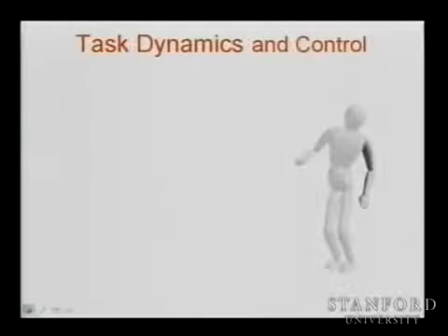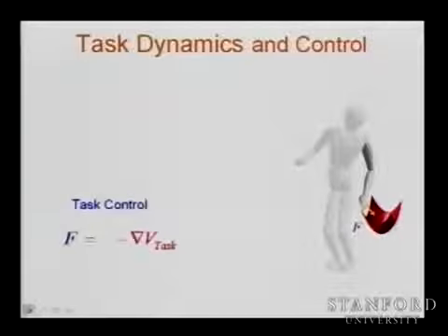Let's go to the arm. That's what we studied earlier. You have a force. You have the gradient of the force. How do we apply it? Torque equals J transpose F. Okay, very simple. That should work. We said we cannot just do it like this. We need to account for the mass properties.